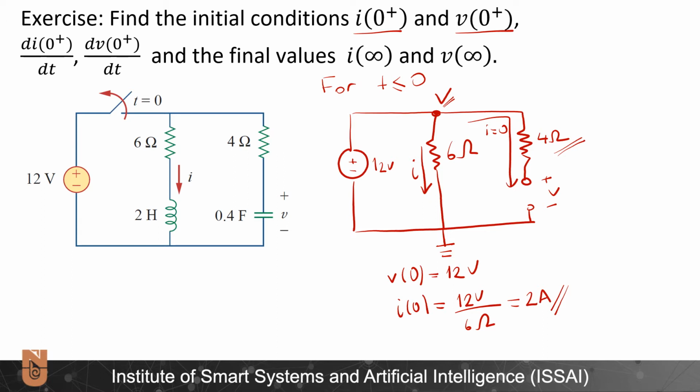You might ask, here we have the plus signs. Why don't these values change when the switch is opened? Because these are integral based variables. In other words, the current over an inductor cannot change instantaneously. The voltage over a capacitor cannot change instantaneously as well. Therefore, I0 minus, I0 and I0 plus will be equal to each other.